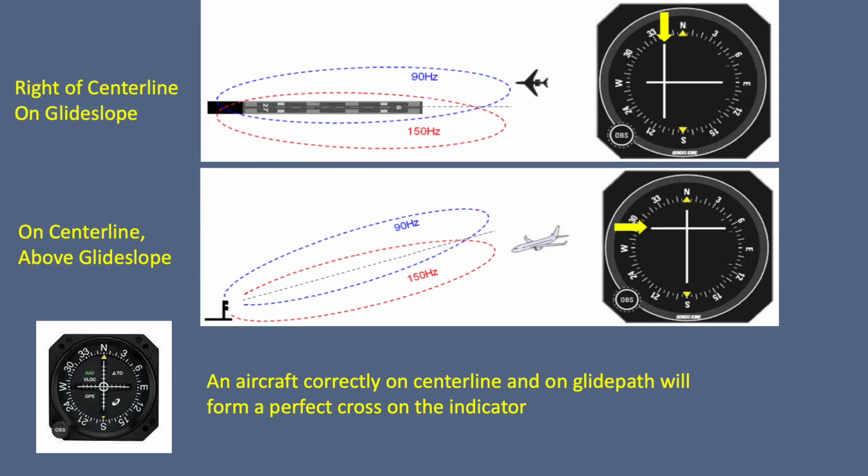The glide slope and localizer are read on a course deviation indicator instrument. The horizontal line is for glide slope, and the vertical line is for the localizer. If the aircraft is vertically and horizontally correct, the lines will center.